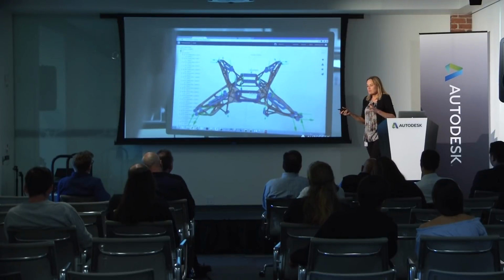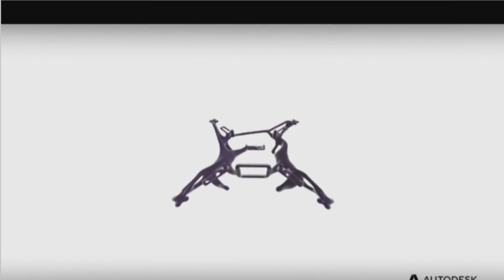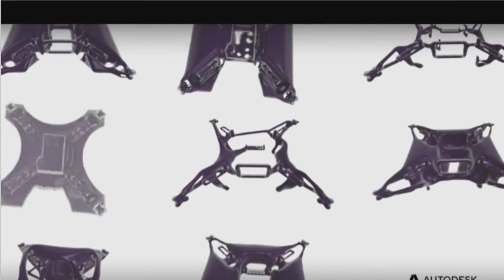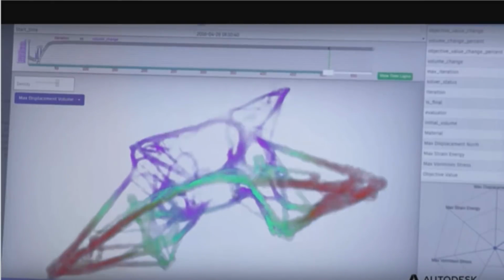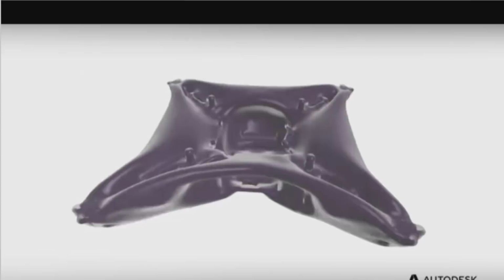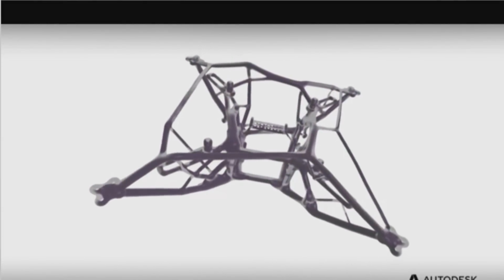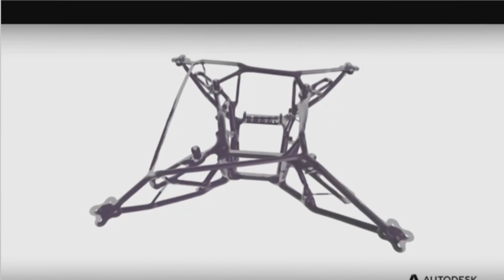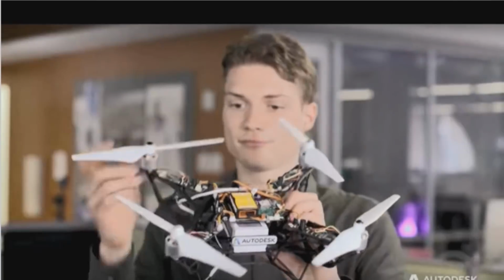Because what the system does is it initially creates a volume of material. On the first iteration, it removes material. At every subsequent iteration, it does a strength analysis to determine how much more material can I remove. Oh, and did I remove too much material? It will add material back. And it will synthesize the form that satisfies your goals and constraints.